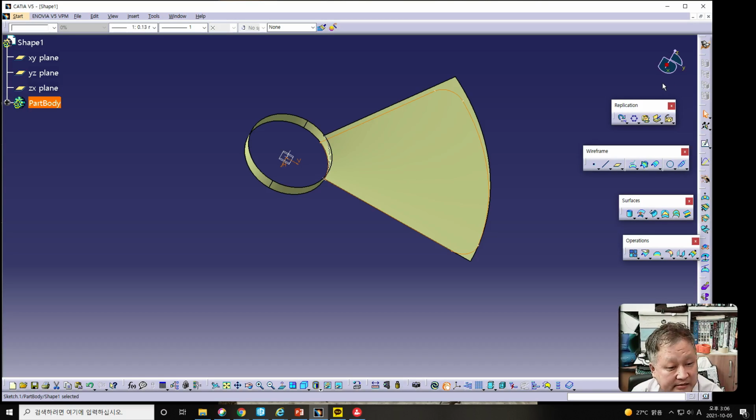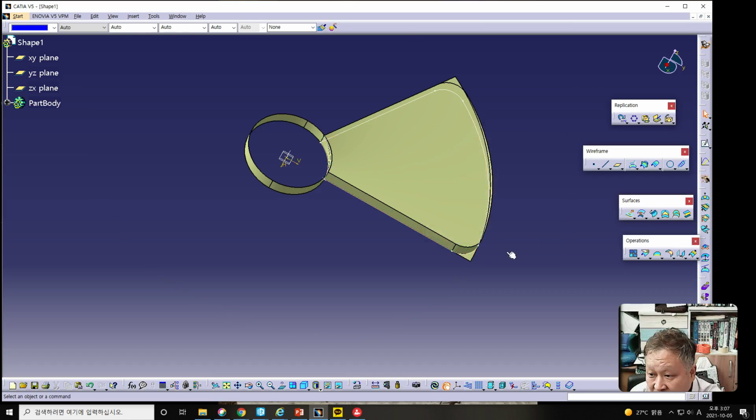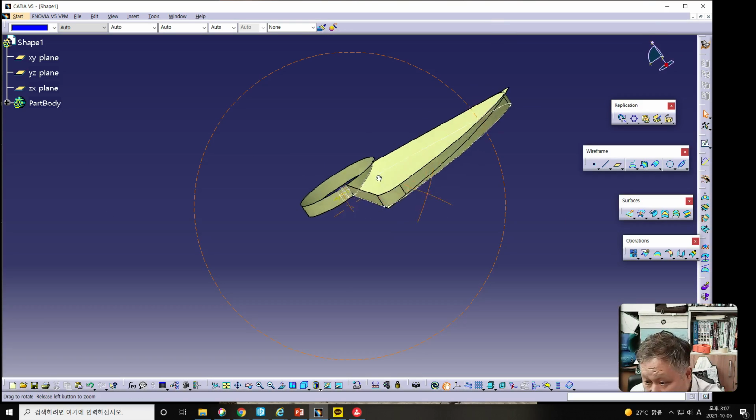And in this case, maybe create a drawing created using Extrude according to the settings above. Maybe you should find the Extrude button first, near cylinder. Extrude sub menu should be selected, and direction 20 millimeter dimension should be needed, and preview, then Extrude can be made from this operation.